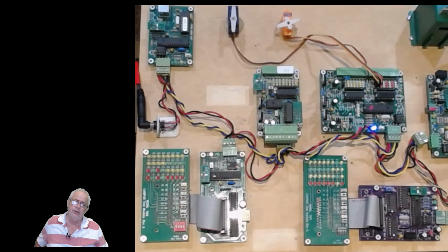Now, this is a real oddbod in the 1Y firmware, and it's in the 4C as well. What happens if I don't click that is whatever my device number I'm using is, so 1001 in this case, if I don't click send short event, it'll actually send a long event with the node number of my CANPAN, node 1001.